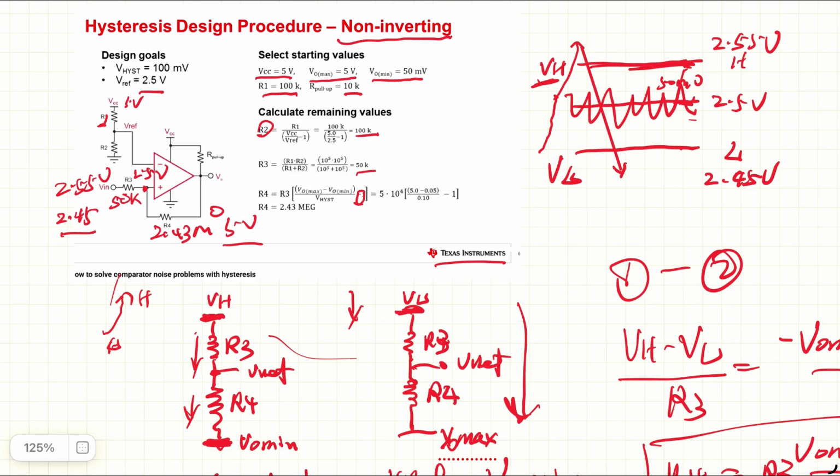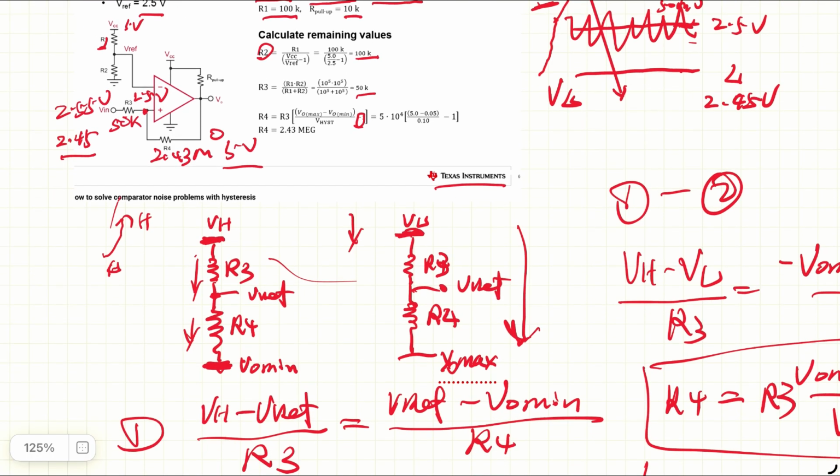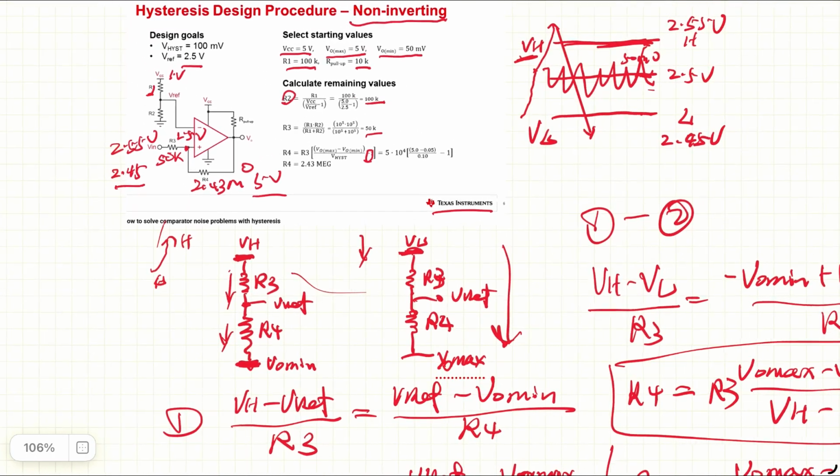Even if you have an input of 2.5 volts and output close to 5 volts, you still get the threshold of 2.5 volts here. How do you set up these ups and downs? It's just by using the voltage divider circuitry and the output, because the output is switching between 0 and 5, low or high. That's what causes this change in threshold values. It's a pretty smart design.